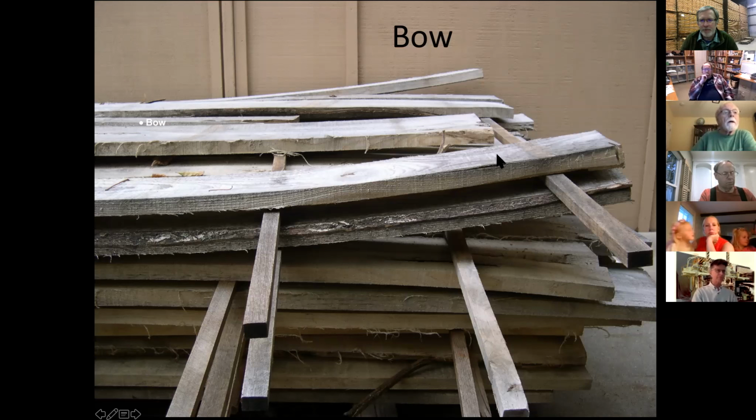So the top surface of these boards, this top part, shrank up to 10 times more than the bottom, which was mature wood, and it causes it to pull up like that. Now, when I say shrink, I mean shrink in length. What causes bow to occur? One surface shrinks more in length than the other. It has to. What else could possibly cause that except holding it in that position while you were drying it, okay? So bow has to be caused by either reaction wood or juvenile wood.